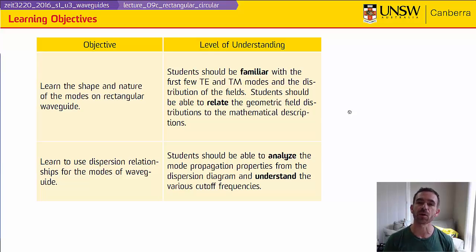So for example, in lab number 2, you're going to go from coaxial waveguide into rectangular waveguide. And whenever you make those transitions, you have to find a way to make the two geometries look enough like each other so that the mode coming in can excite the mode going out. And you'll see an example of that when you do your laboratory number 2. And this is a common theme that comes into play when you're dealing with microwave circuits.